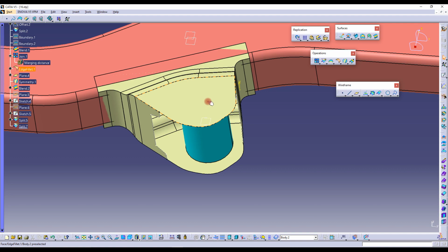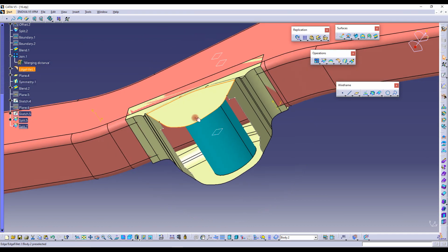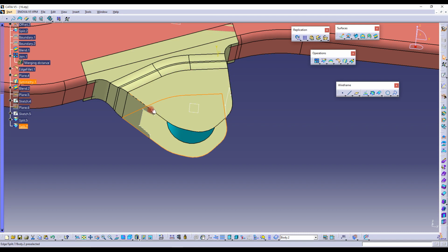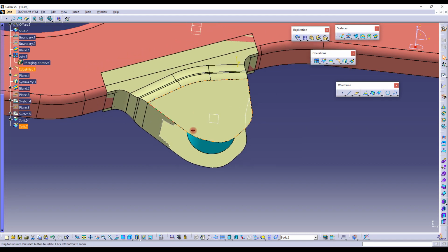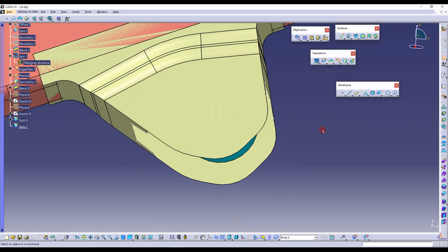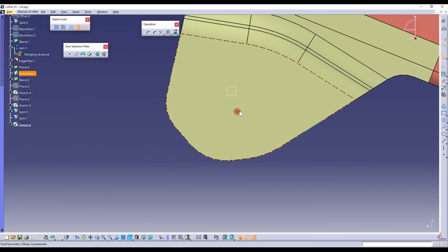One more cutout which we require is the cutout on these two butting faces. So that cutout is for giving the fillet for this edge. So this edge we cannot give the fillet directly, because if we give the fillet, then it's going to ride on top of this line, and which is not going to create a good fillet, which will not be manufacturable. So for that, we need to create another sketch on this plane.